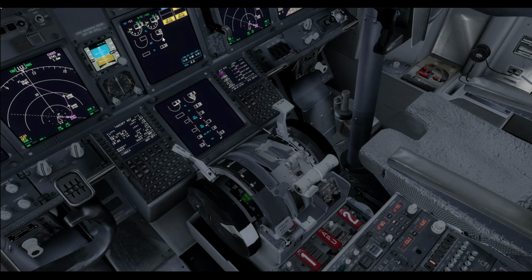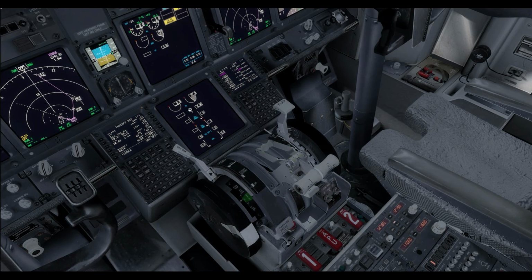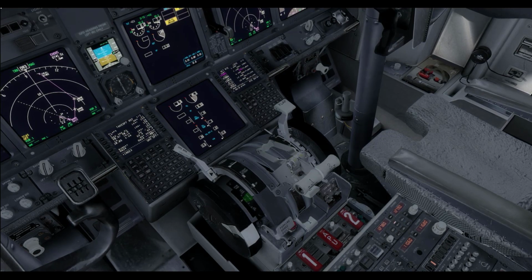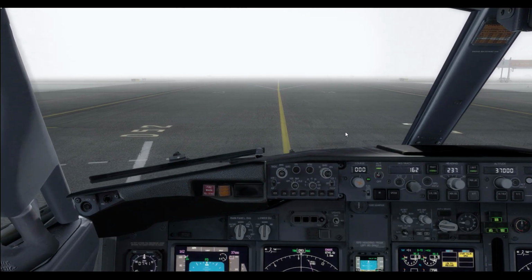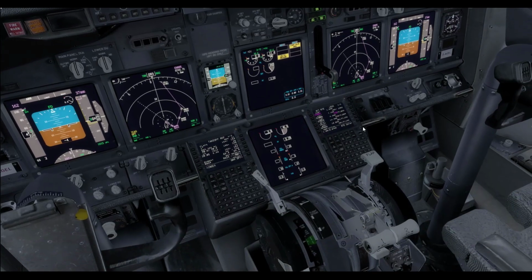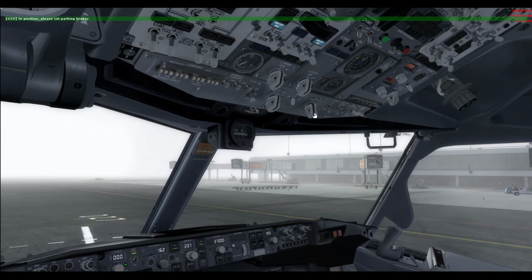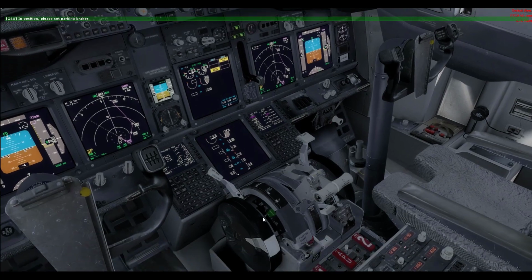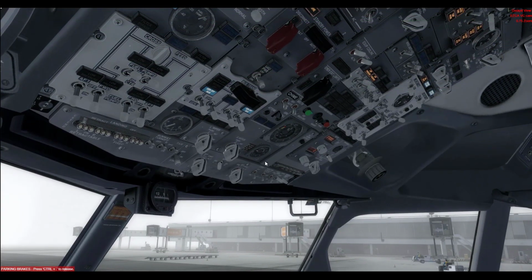and now you can see the EGT rises, which is the exhaust gas temperature, and the oil pressure again further rises. You can see the fuel flow is positive now. Wow, you can't really see a thing. Now once the engine is started up, you will see this, set the parking brakes. You will see this lever go back to off, and then you have done everything right.